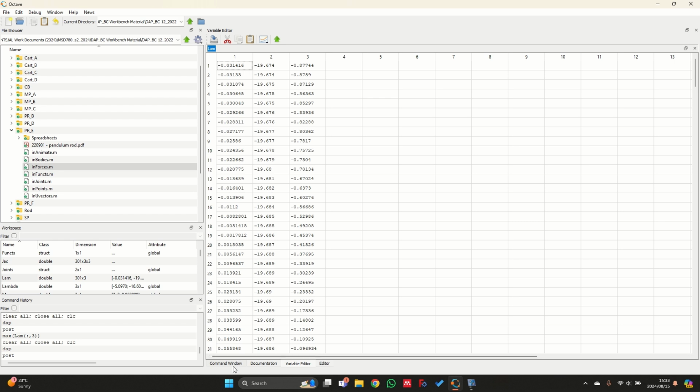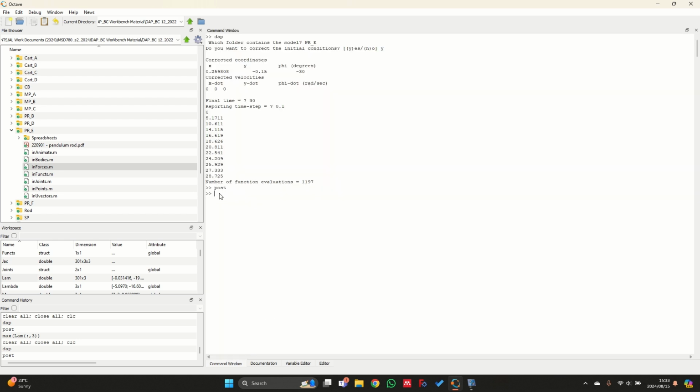So what this basically tells us is that although I'm specifying that 6 Newton meter torque, what the relative rotation driver will actually do is apply a braking torque once I reach that 2 pi over 60 radians per second square acceleration that I specify. And that will ensure that across the entire 30 seconds that this thing runs, the rotational acceleration will remain constant in accordance with the actual relative rotation driver function.